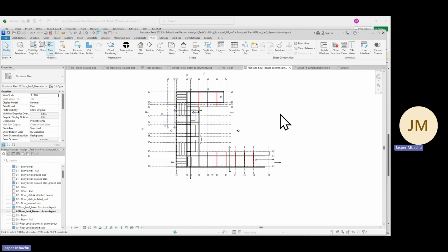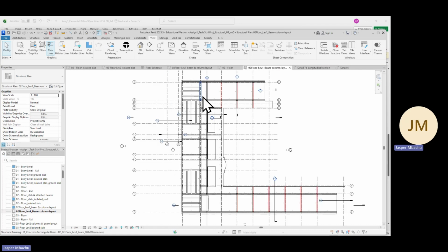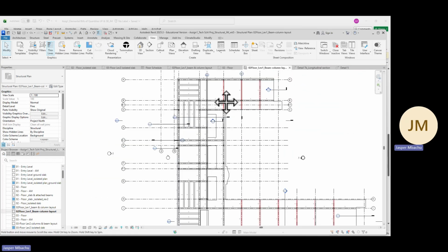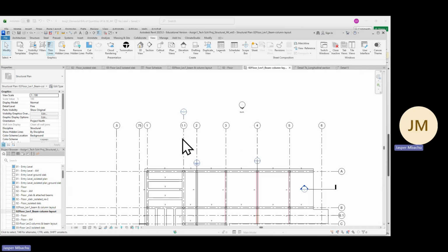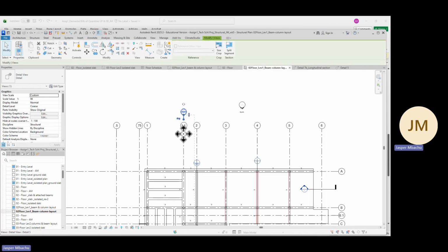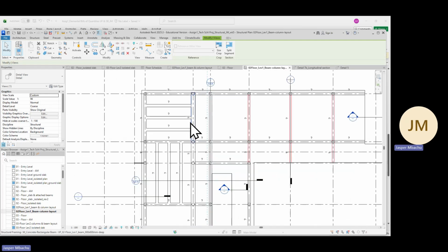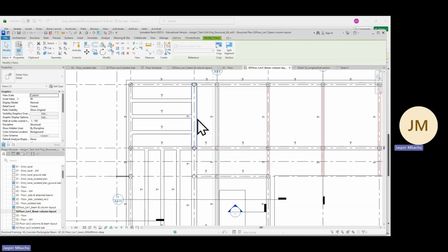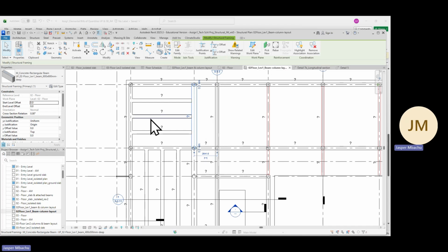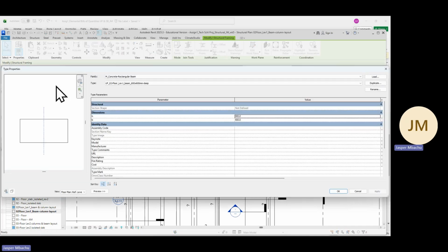Now go to that grid line 1.1, vertical grid line 1.1. Click one of those beams, because if you zoom here on this grid line 1.1, if you have not made this to show, make it show any of the beams on this grid line, click on it and go to edit type. You see the type that you saw there could be 600 by 900, isn't it?